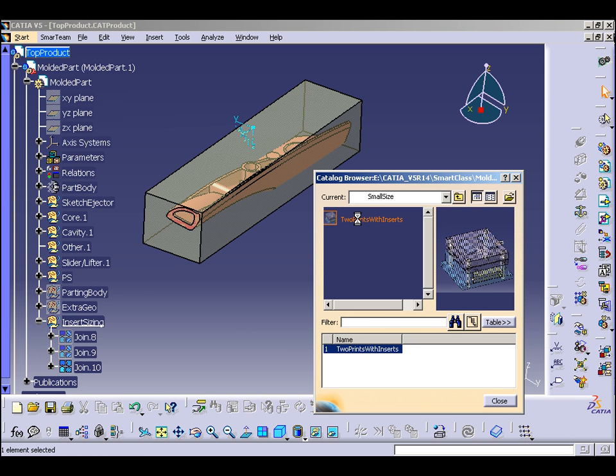The mold tool for the handle part is created from a user-defined assembly template stored in a catalog shared inside the company. The template contains the 3D assembly definition, mold plates, rough insert blocks, various standard components like leader pins, screws, ejectors, and so on.